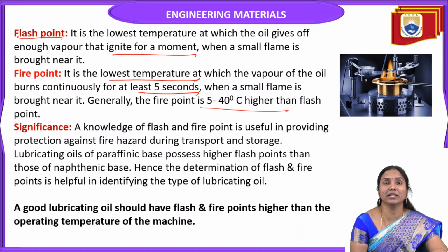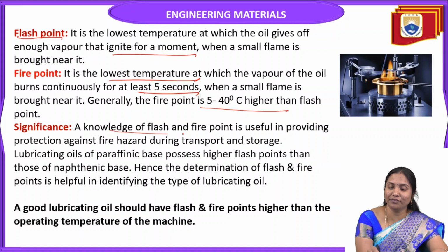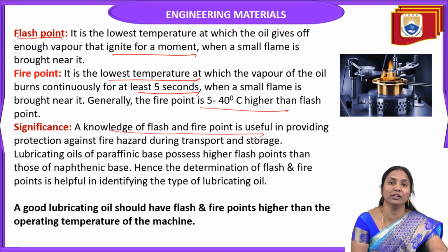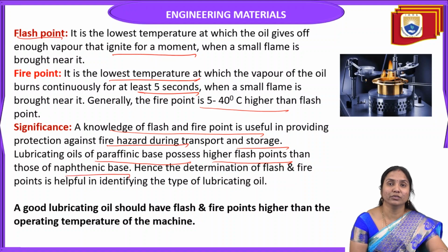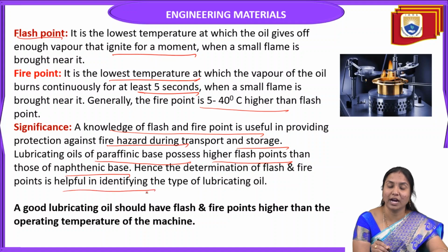What is the significance or importance of flash point and fire point? Knowledge of flash point and fire point is useful in providing protection against fire hazards during transport and storage. Lubricating oils of paraffinic base possess a higher flash point than those of naphthenic base. Hence the determination of flash point and fire point is helpful in identifying the type of lubricating oil.